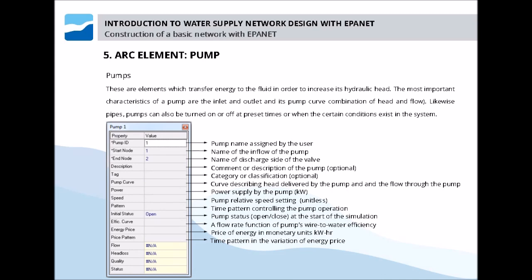Pumps are another arc element. These are elements which transfer energy to the fluid in order to increase its hydraulic head. The most important characteristics of a pump are the inlets and outlets, and the pump's curve, which is actually the relation between head and flow.